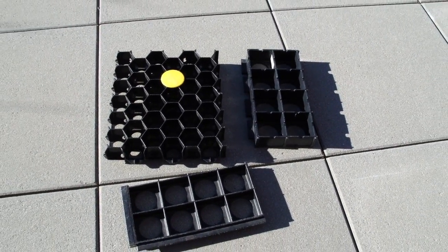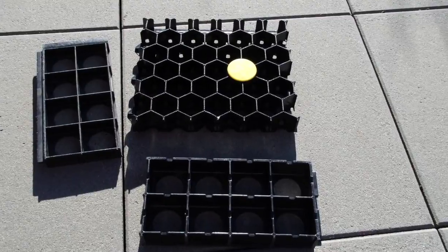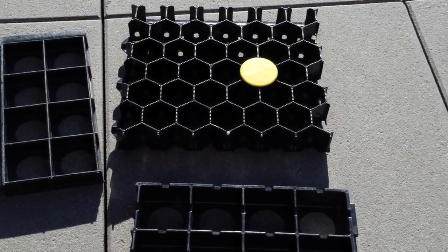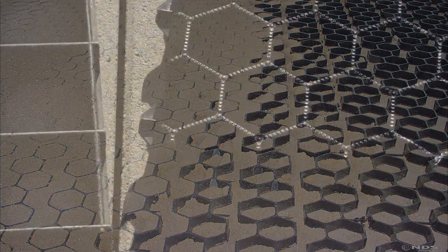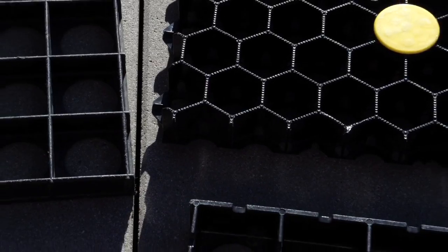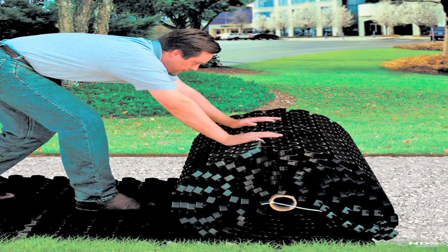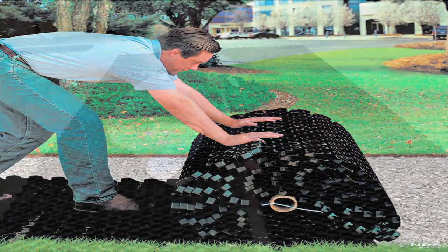So you could basically fill these cells either with no fines kind of gravel, so you can have porous gravel if that's the look you want to have. I have a project over in Suquamish where we did the fire lane that way, and I filled the inner 12 feet as a gravel lane and the outer 4 feet on either side with grass to make it blend in. It's capable of high loads.